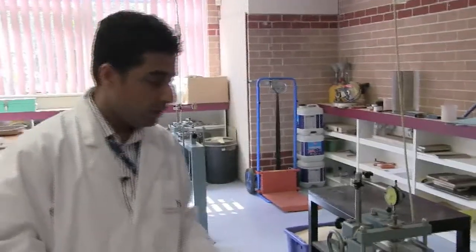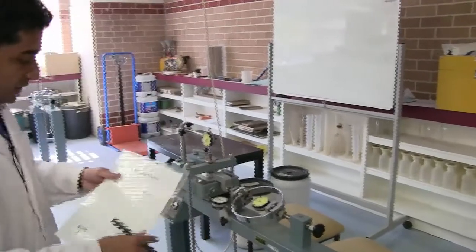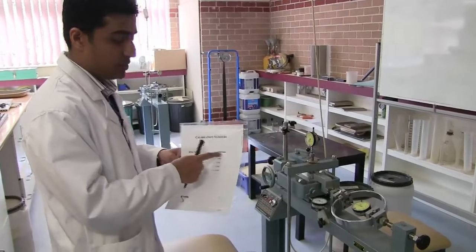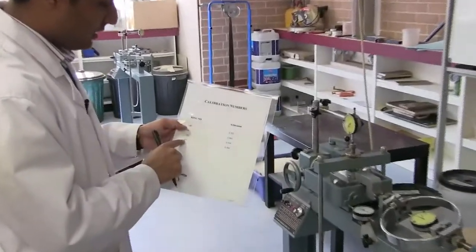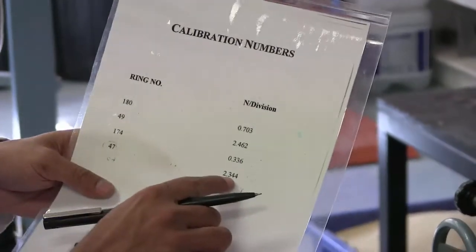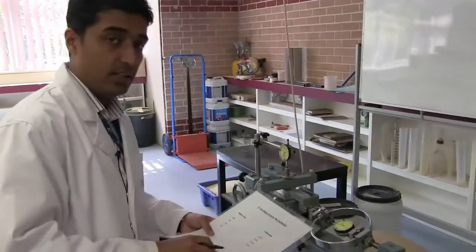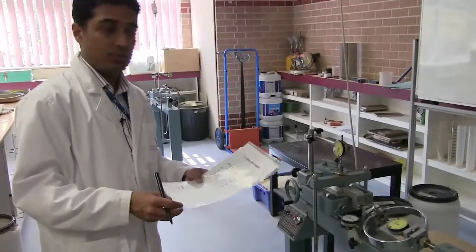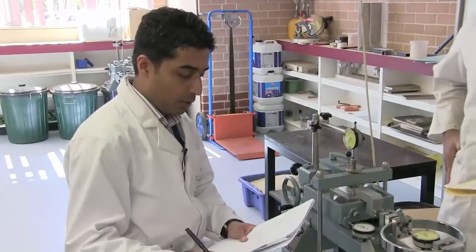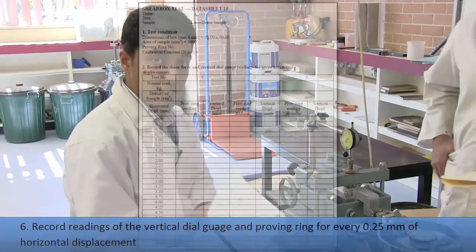Okay, so this proving ring is proving number 47, and for each proving number we have a calibration number, the newtons per division. So proving number 47, the number of newtons per division is 2.344. You multiply this value by the proving ring reading, and it will give you the shear force of the soil at that particular displacement. Okay, now once everything is set up, we are going to take down the readings in data sheet number 10.